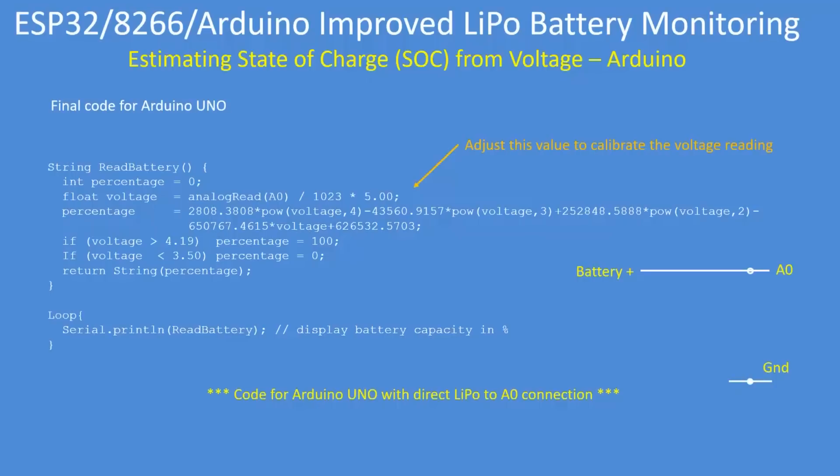For the Arduino Uno, its normal input range of an ADC is 0 to 5 volts, so it makes it easy to scale the values, but again, no difference in the function or equations other than getting that analog input voltage on A0 or A1 or 2 or 3 or 4 or 5. Change the voltage analog read line accordingly.